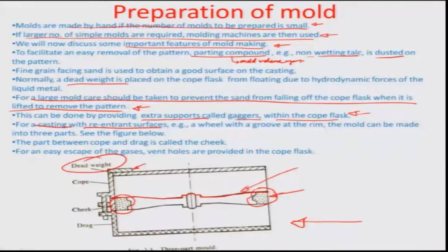Okay. So this surface is basically preventing the metal from flowing out, so that this cross section of the wheel can be obtained. It is a circular pattern that we are talking about in this particular case. And so this shape is only obtained because you give additional sand, re-entrant sand here once the patterning has been done, and it will prevent the metal from going into this place.